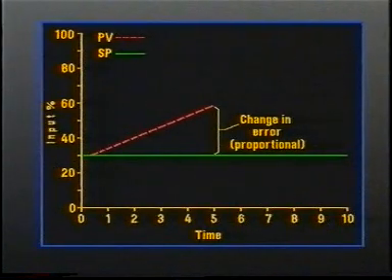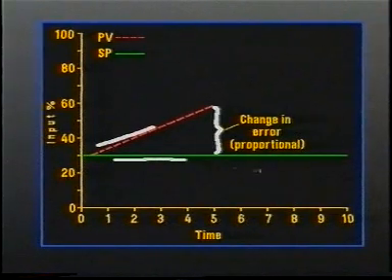Proportional control action deals with the value of a process error as it occurs by comparing the value of the controlled variable to its set point in order to establish the presence and extent of error. The controller then provides a control signal that is computed in a preset proportion to the amount of error. This proportion, which is the output of the controller divided by its input, is also called the proportional gain.